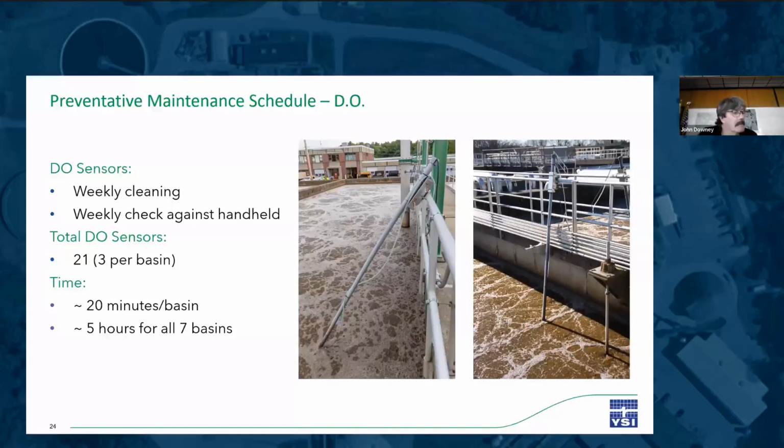in different sites. When I move over to the south, because we're using dissolved oxygen as the control point, rather than just place that sensor in hold, I change the control strategy over to airflow mode. And I let the chief operator know that we're doing that, so he'll know that we've changed the process logic a little bit during the cleaning cycle. Once the sensors are back in the basin, they return to the actual concentration of DO in the water fairly quickly. And after that, I can switch control back over to DO mode.